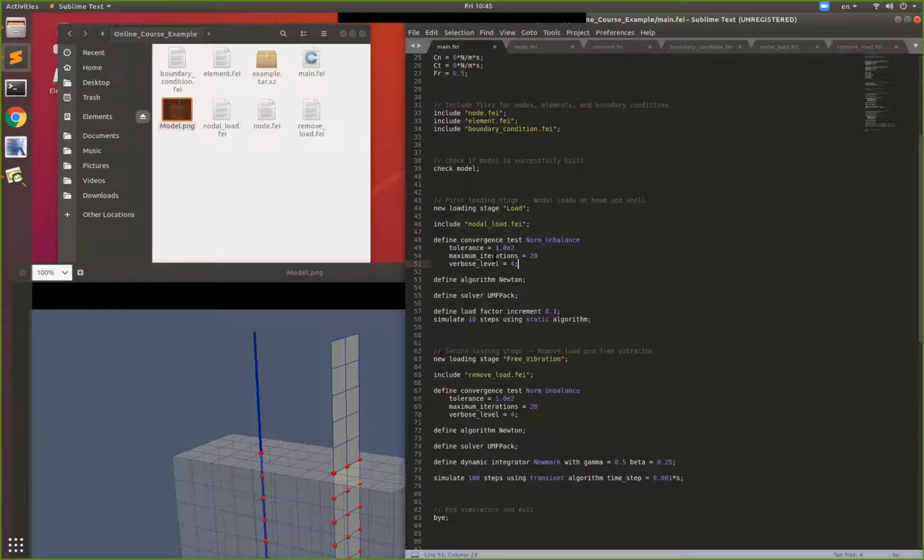And if I may add, it's a nonlinear system because of those interface elements, and you're going to use Newton to solve that. And what you're requiring the system is to go back to equilibrium within some tolerance, and then you define the tolerance. Excellent. Go ahead. Yes, and then we say, okay, for each step, you have a maximum number of iterations